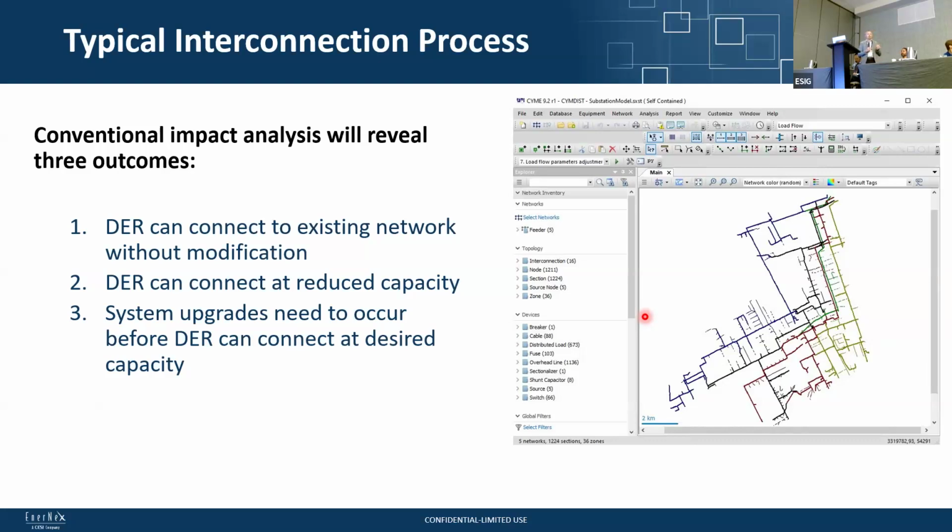Really, what flexible interconnection is designed to do is create a fourth option where we've run some analysis, which Mark will touch on, and we see that there are certain periods or situations where yes, you will violate the limit, but other times you can be at full nameplate capacity. That's the whole crux of flexible interconnection: allowing for that flexibility in the connection process.